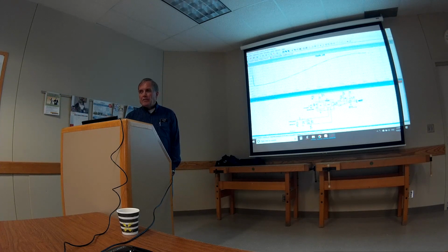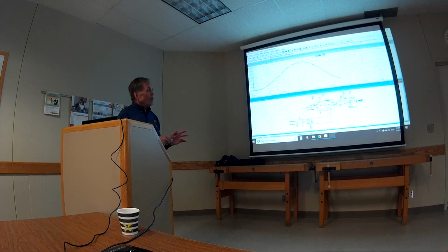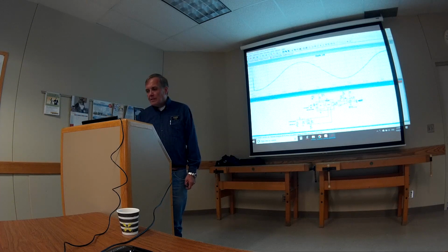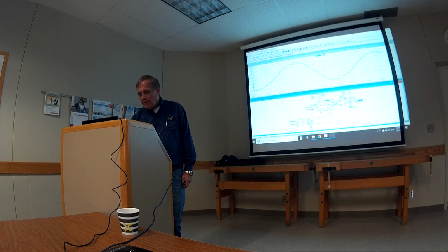I want to do the FFT of the audio waveform to see what frequency it's at, just for the fun of it. You have to wait just a little bit here. See a little notch in there, by the way. I don't know what that notch was from. There's some component in there that's giving it a little bit of that in every waveform. This is really exact because of the model that's being used. You wouldn't see that in real life, but it's there in the model. You could go back and analyze what part of the model is making that little notch. But every waveform, every time it comes down, it's going to have that little notch there. Wait just a little bit more here, and then we'll take an FFT view of it.